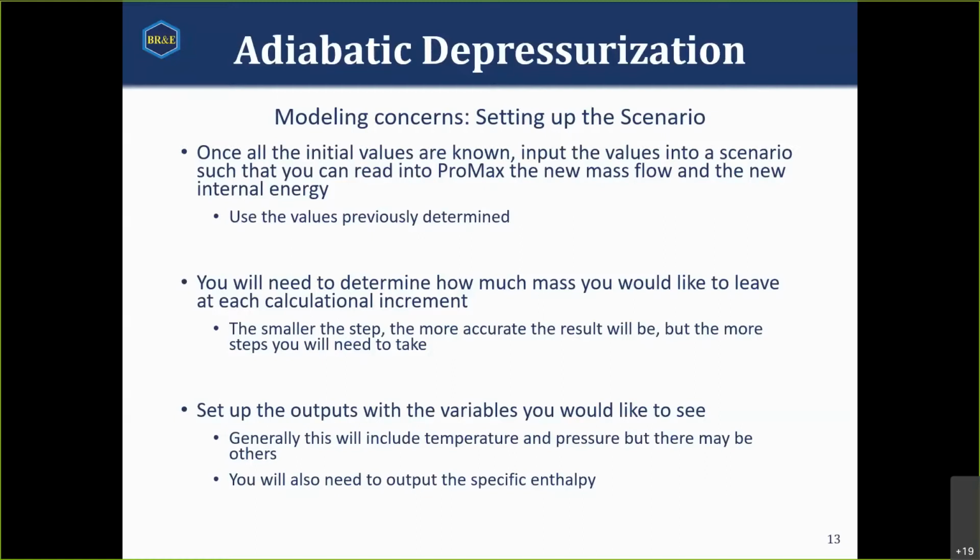Obviously, in reality this would not be discrete, but a continuous function. In ProMax, because it's a steady state simulator, we will be doing this in discrete increments. The smaller your increment, the less mass you remove at each step, the more accurate the result will be, but the longer it'll take to get there. How many steps you want to take is entirely up to you.